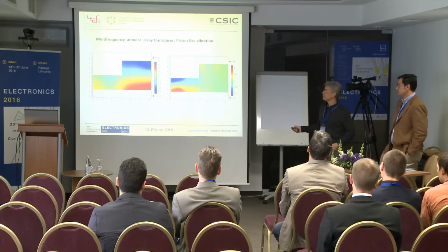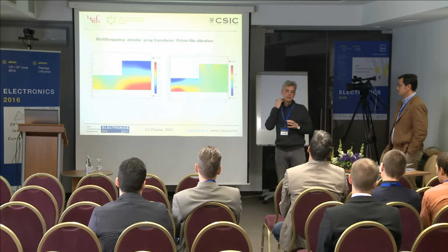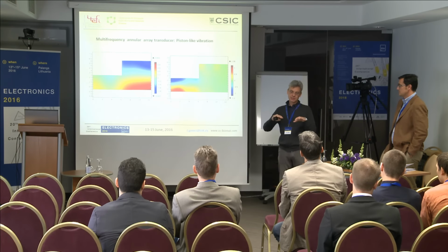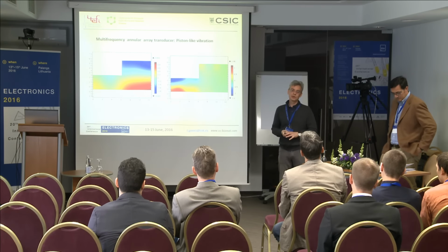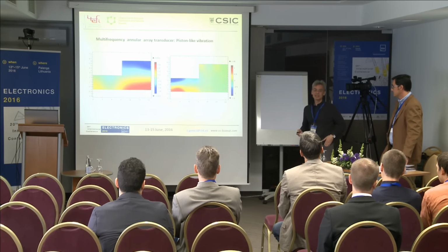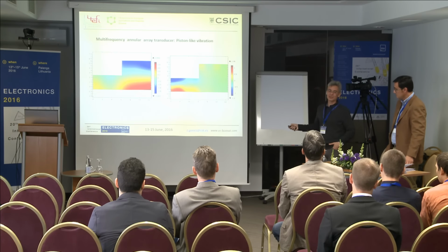Well, what you have is the coupling between the two elements through the epoxy. So another idea would be to use a softer epoxy for that. The softer the epoxy, the lower this lateral coupling. So at the beginning, we hoped that using a 1-3 connectivity transducer was enough to avoid this crosstalk here.